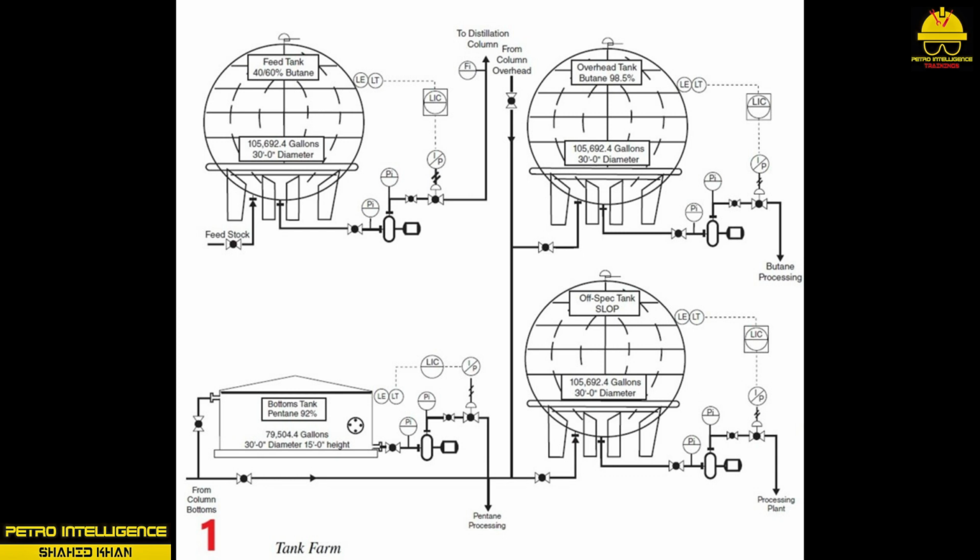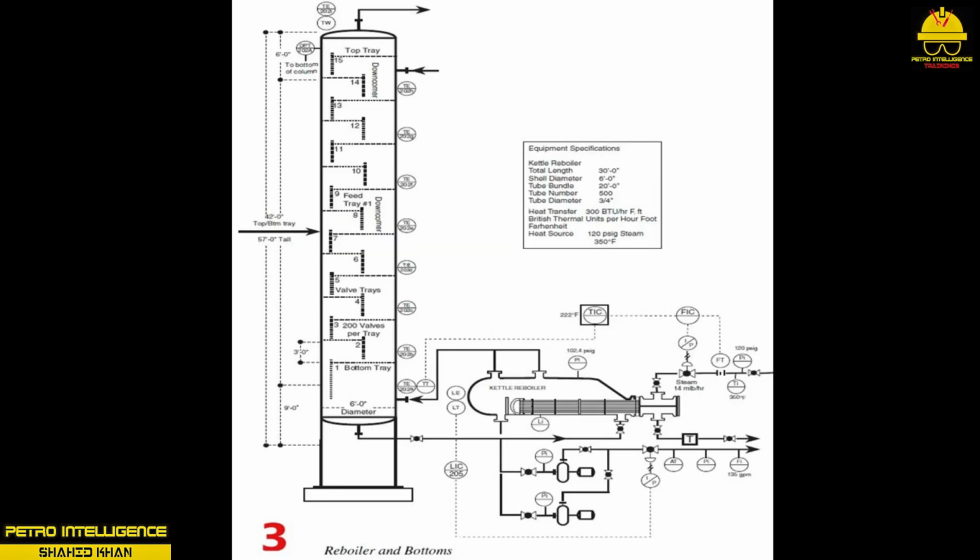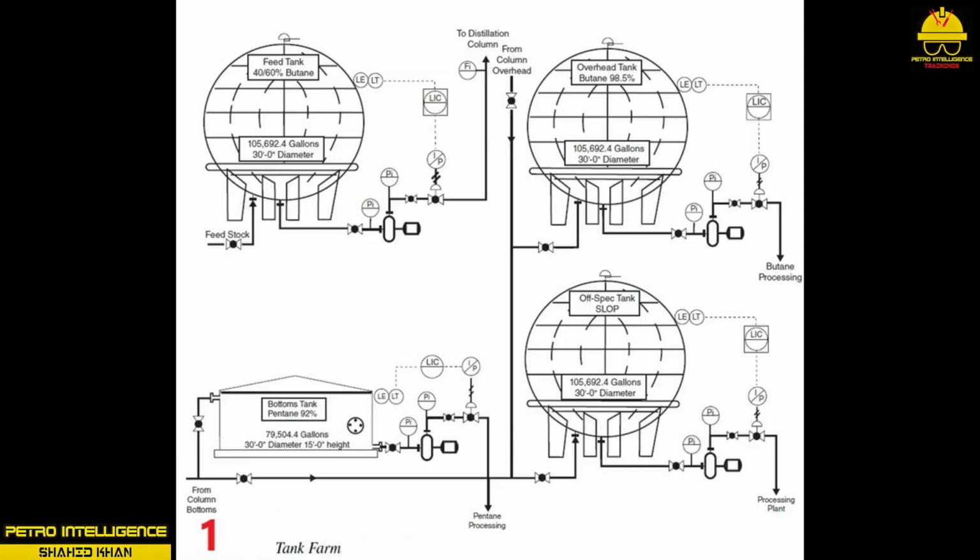20. Start unit feed pump. Watch levels in accumulator and reboiler. 21. Cascade kettle reboiler steam FIC to TIC. 22. Start bottom and overhead pumps. Do not start without a level. 23. Line up and start off-spec tank pump. 24. Heat, catch sample on overhead and bottom product. Take samples to lab.